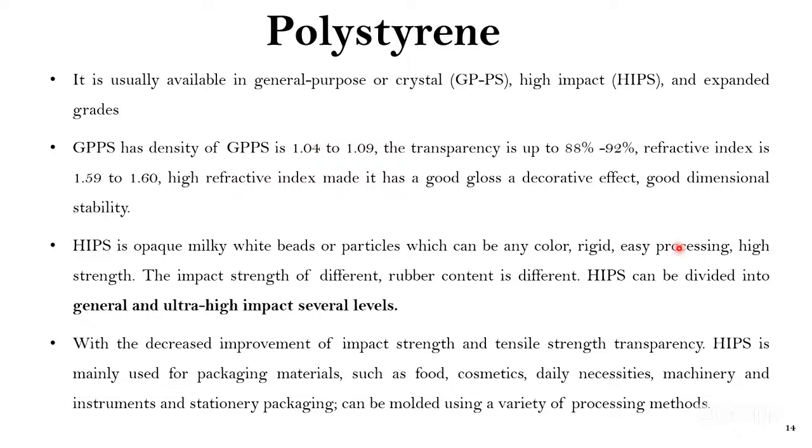Semi-crystalline. This property only tells us this is semi-crystalline. Maybe it has 60 to 70% crystallinity. That's why it has an opaque nature. See, the concept behind amorphous and crystalline: the more the crystallinity increases, the less transparency you will receive, and it moves towards opaque. Is that clear?